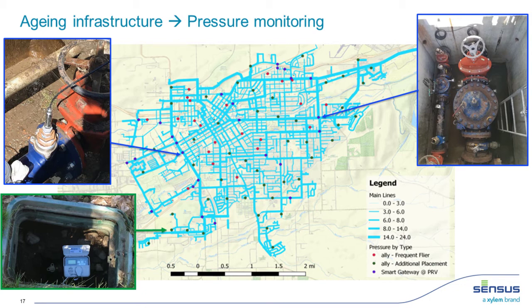And so kind of going on that same theme of pressure monitoring, and I see pressure monitoring as really the gateway to more distribution monitoring. This is an example of one utility that leveraged their AMI system along with a smart meter with an integrated pressure sensor, you're seeing down at the bottom left there, along with a radio over the AMI system hooked up to just your standard bullet pressure transducer shown on the top left and right.